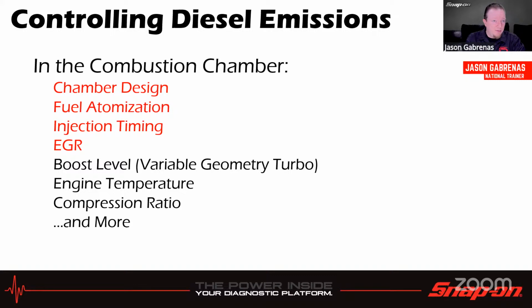There are a couple of ways we can do it. We can do it within the combustion chamber by using different chamber designs, different ways of atomizing the fuel, different injection timing, and EGR valves, for example, which we're going to talk about. Also different boost levels using variable geometry turbos, engine temperature controls, compression ratios, and more.